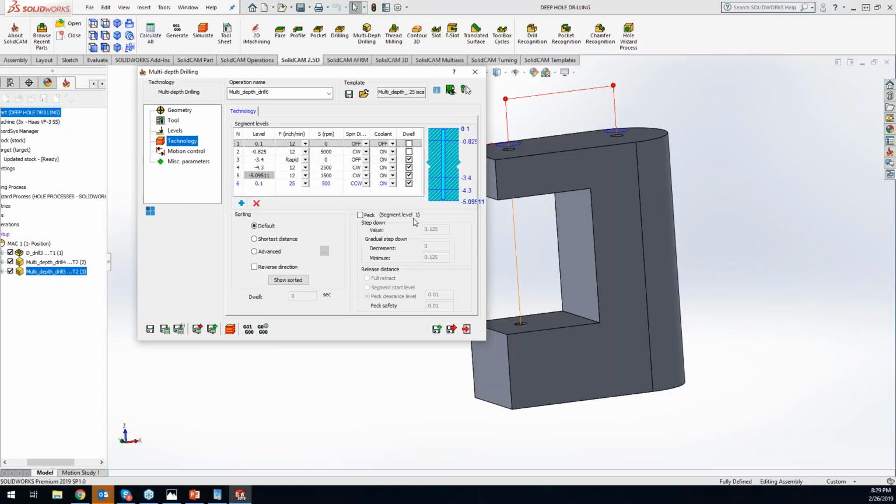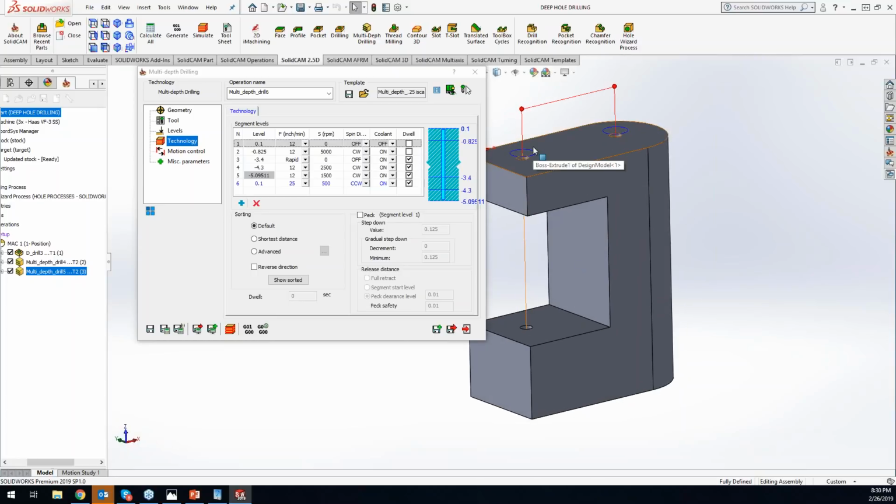There is one, Kev, and I think it's an interesting one too. Can you circular interpolate a hole with the final pass being repeated infinitely, and then the tool feed back out of the work? So circular interpolation is a little bit different than drilling. Circular interpolation is going to be actually a profile operation. So if you guys are looking to do a circular interpolation of something like this, then what we'd want to do is switch you over to a profile operation. Drilling is just going to be a straight vertical Z move. We don't have any control to do a circular interpolation with the X and Y axes.